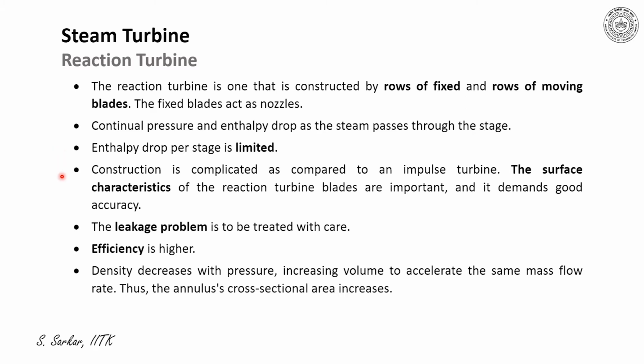Furthermore, the construction of a reaction turbine is complicated as compared to an impulse turbine, where the surface characteristics of blades are important and it demands high accuracy. The leakage problem here is to be treated with care. Efficiency is higher as compared to an impulse turbine.